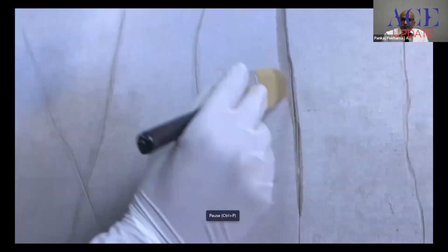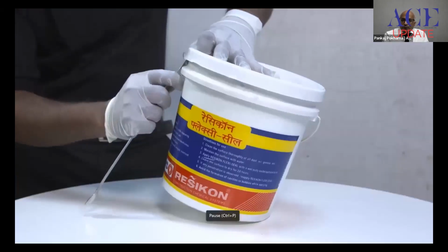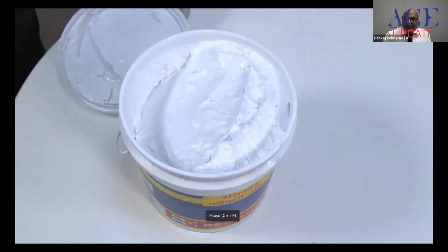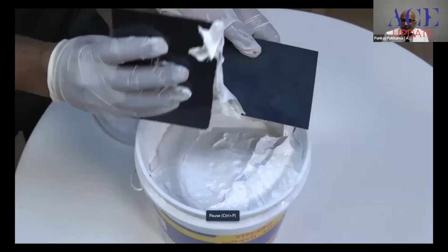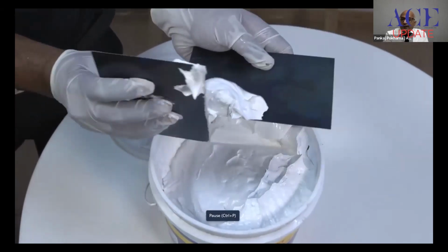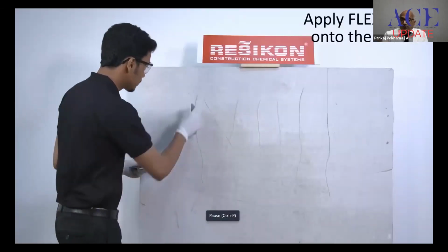You have to wash the crack so that all dirt comes out of the crack during opening of the crack. You have to take this paste, acrylic paste, which is pure acrylic, elastomeric and flexible in nature.